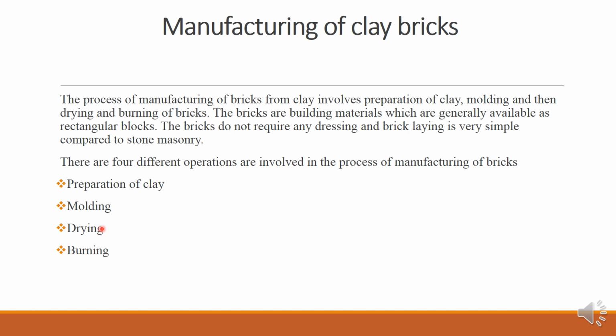The bricks in these stacks should be arranged in such a way that circulation of air between the bricks is free. The period of drying may be 3 to 10 days. It also depends upon the weather condition. The drying yards are also prepared at a higher level than normal ground to protect the bricks from rainwater. In some situations, artificial drying is adopted under special dryers or hot gases.